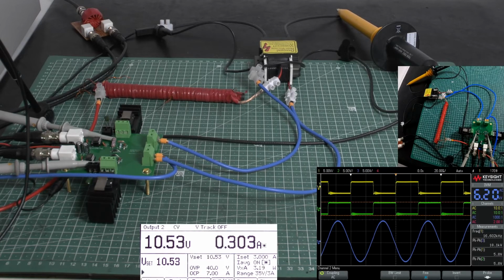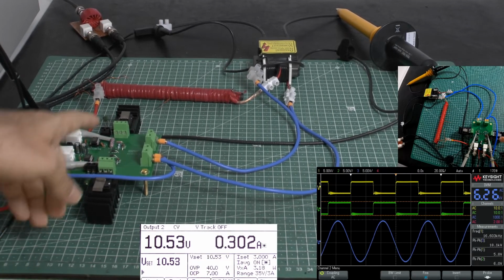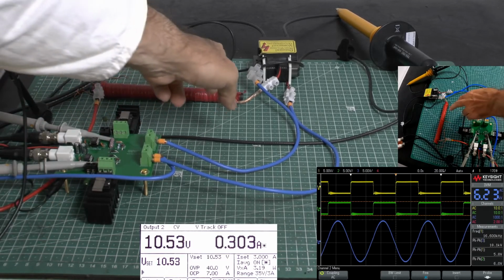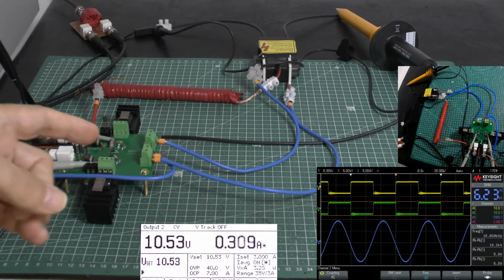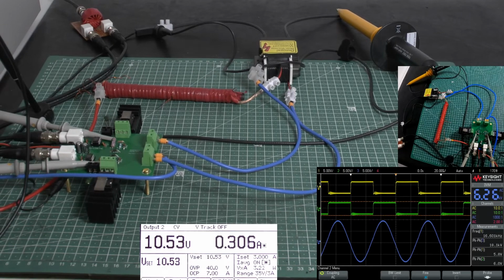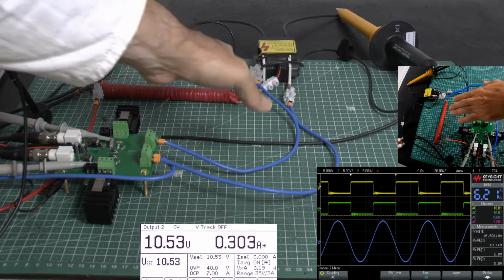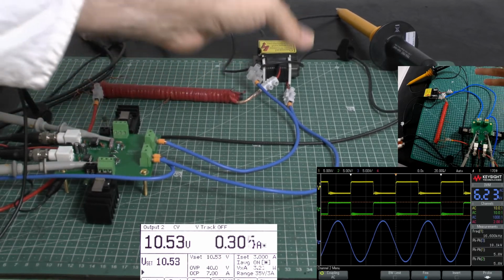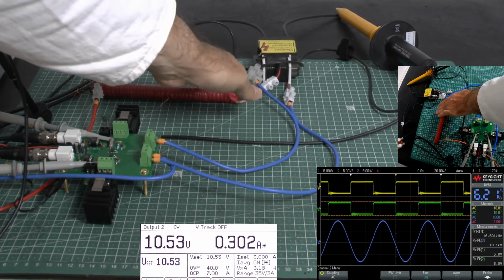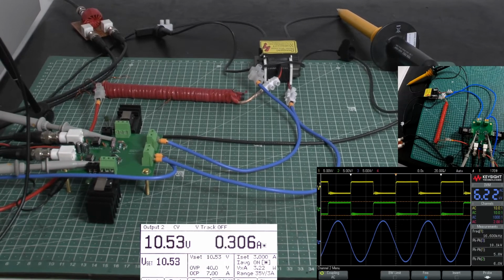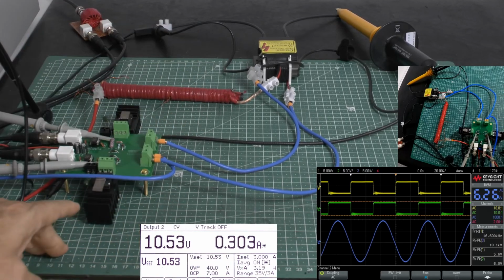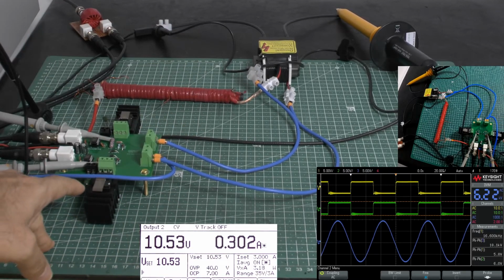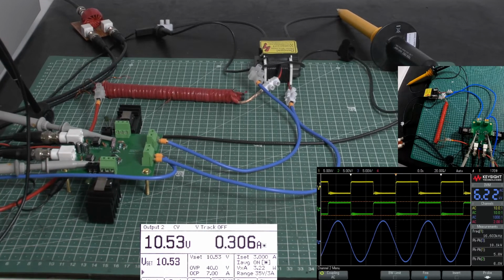If you look at the waveform here on top and right, you see a little ringing. This is also because we have the smoothing capacitors on both sides for the gate, and because we also use, in the center for the primary coil, an inductor, which allows us to store energy in each cycle into the primary, and also reduces the back EMF coming through because it works also as a filter. So we have very, very little ripple. That means it's not required to use an RC snubber circuit in this kind of configuration. And with a little smoothing capacitor, we have a very, very clean signal here without any kind of problem.